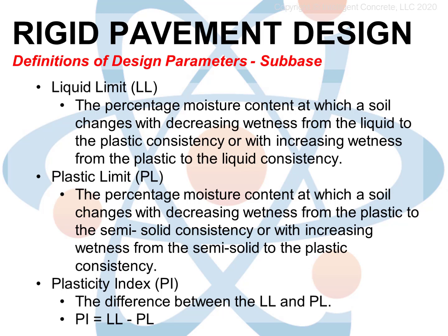The liquid limit is the percent moisture that causes a soil sample to turn from a plastic consistency that is able to be formed into a narrow cylinder or a thin ribbon by rolling or pressing between one's fingers into a liquid like mud, and the whole thing falls apart.